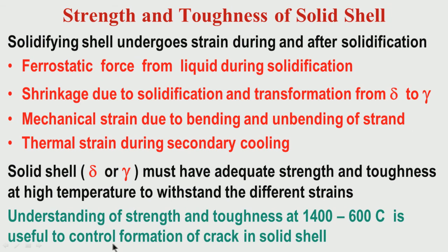So these issues are important for controlling formation of crack in solid shell. If we can control formation of crack, we will have a relatively good quality of solid shell, the cast product will be relatively good, we need not worry about it during subsequent processing of it.